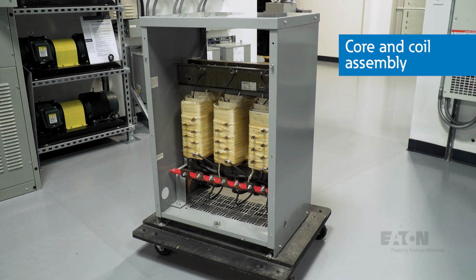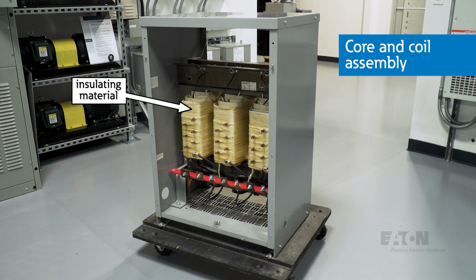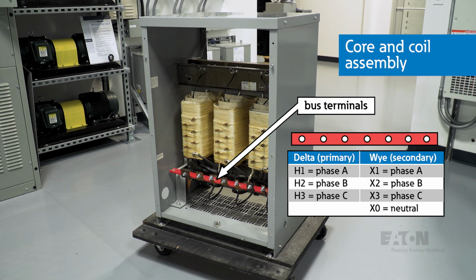Here you see a transformer with the enclosure removed, commonly referred to as the core and coil assembly. This image is a three-phase transformer, as evidenced by the 6 individual coils, one for each phase on the primary and secondary. The core steel is found inside of each coil. The secondary winding is wound around the core, followed by the primary winding. Each winding is surrounded by an insulating material to protect the winding and keep them fully isolated from making contact with themselves or the core steel. The end of each winding is then brought out to bus terminals, which are mounted in a horizontal row onto a terminal board.